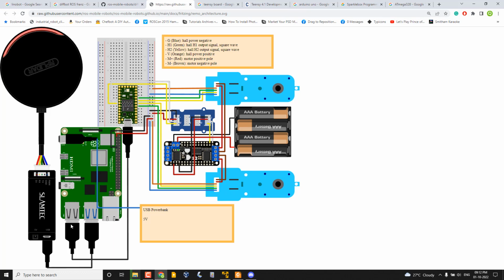Okay, that is called ROS serial. The intention is that using the ROS serial protocol, we can send or receive data from a ROS based computer. And that is not the main point, but you can make an embedded system a ROS node.